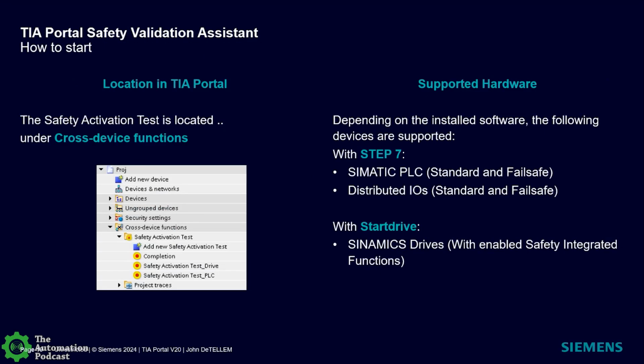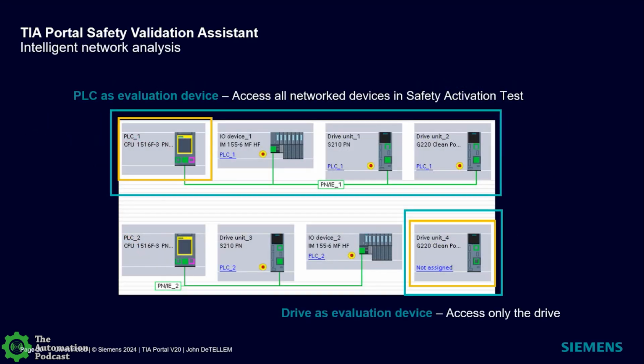Here it is shown where it exists. And fundamentally, what I like about it, it's defined for supporting all the standard PLCs, distributed I/Os, and then the drives, SINAMICS drives, G120s in that. Here's a nice screenshot that shows my safety PLC with some network devices that are part of its safety circuit.